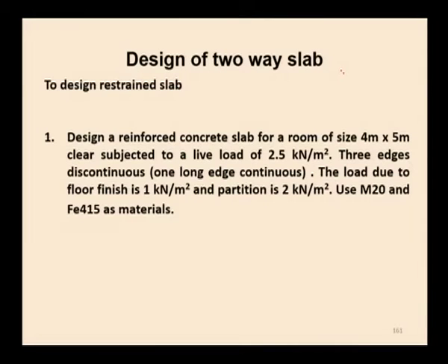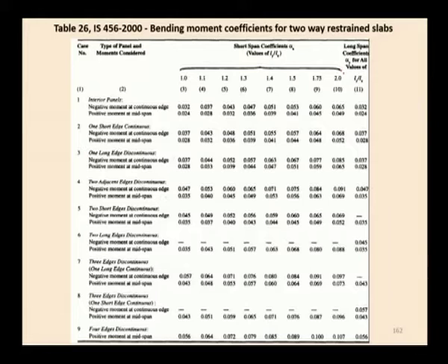That is the condition: 3 edges discontinuous, 1 long edge continuous. So, we are going to use these moment coefficients for finding the bending moment for 3 edges discontinuous and 1 long edge continuous.